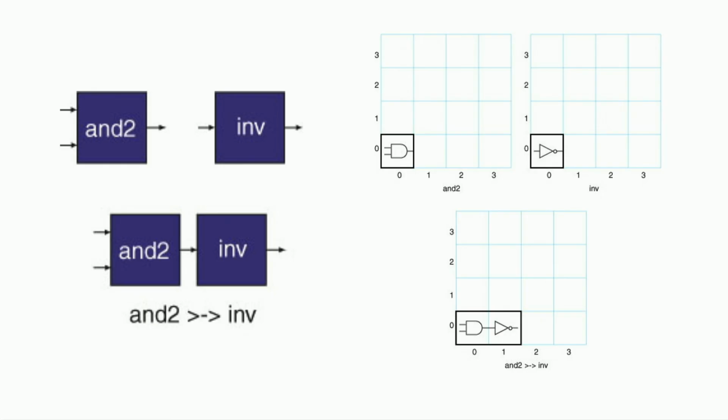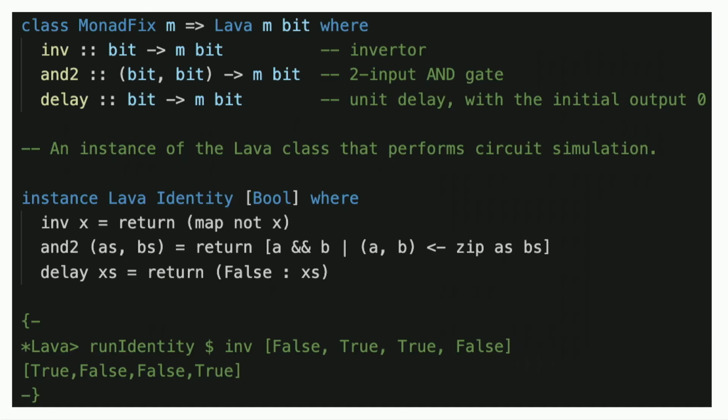Behind this, these Lava descriptions are these individual gates where we compose behavior and layout. And each gate is in its own coordinate system, in its grid. And when you compose them, Lava will know the width and height of each cell. And if you're doing a serial left-right composition, it will shift something along by the appropriate amount, and you get a result back in a new layout grid. Very much inspired by this work done on Escher's fish by Peter Henderson at Oxford.